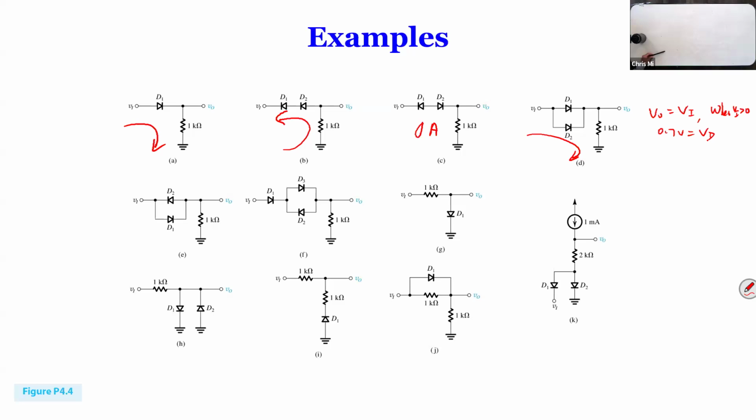It's just that the current continues to increase, so you increase your current capability. If one diode can conduct 5 milliamps, now two can conduct 10. If you exceed 10, it's not breakdown, it's actually burning up. It doesn't protect against breakdown just because you have two in parallel.